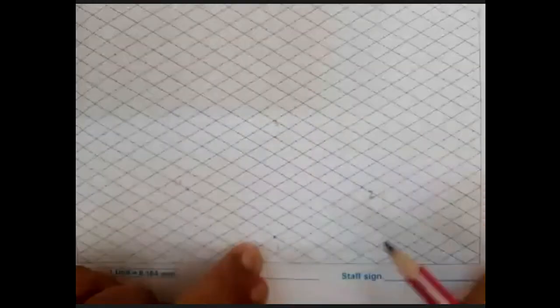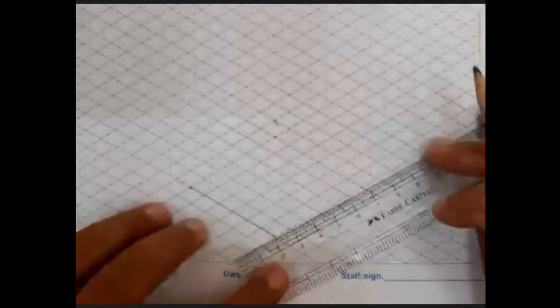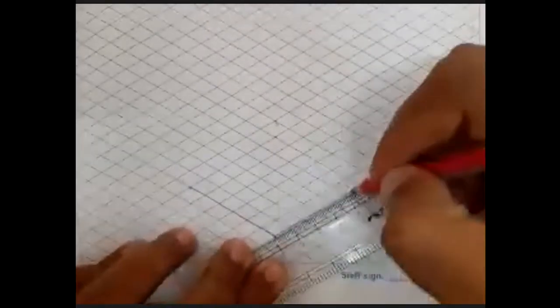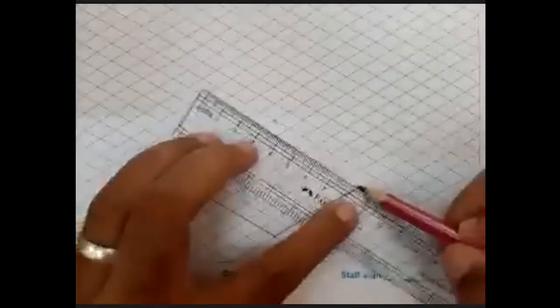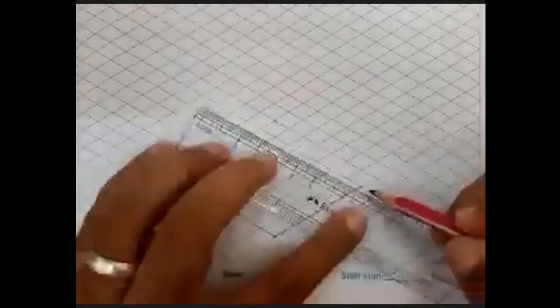So I've got all the 4 corners. That is, this is corner 1, 2, 3, and 4. You don't write these 1, 2, 3, and 4 again. This is for your understanding. I'm writing it, but it should not be written here in the isometric projection lines. So I just draw a square now, on this 30-degree line.